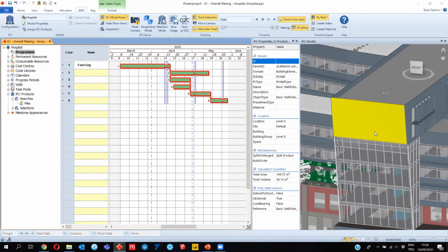Or, for example, we use the GIS information with the schedule during the BI export. Once we export all the schedule and project data into the BI application, for example Power BI, we use the longitude and latitude information to locate where exactly our project is going on, especially if you're working with multiple projects.